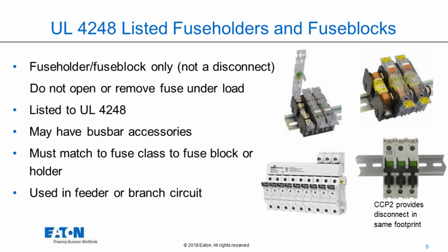It's actually three-pole holders fed at the top by a power terminal adapter. That's a 3-phase adapter. You can get a single or 3-phase. So this comb bus in between the modular holders and the adapter is supplying 3-phase power to the three-pole holders.